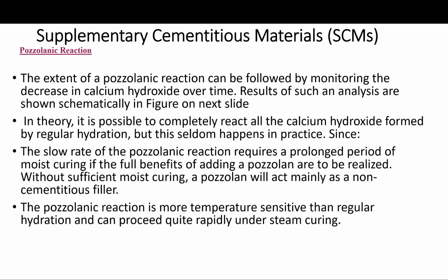Okay, so let's see how we monitor the pozzolanic reactions. The extent of a pozzolanic reaction can be followed by monitoring the decrease in the calcium hydroxide over time. The results of such an analysis are shown on the figure in the next slide. I'll talk about it in a minute. So in theory, it is possible to completely react all the calcium hydroxide formed by regular hydration, but this really seldom happens in practice. So theoretically it's possible, but not the case in reality.